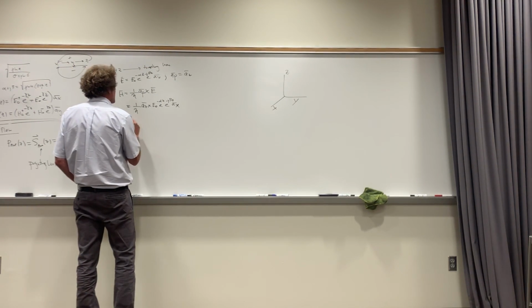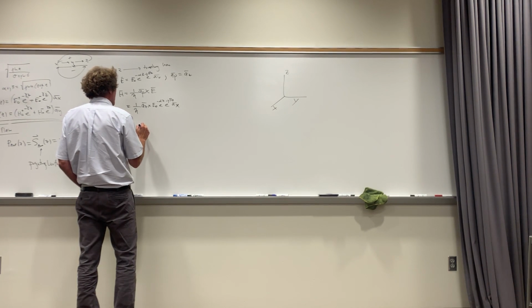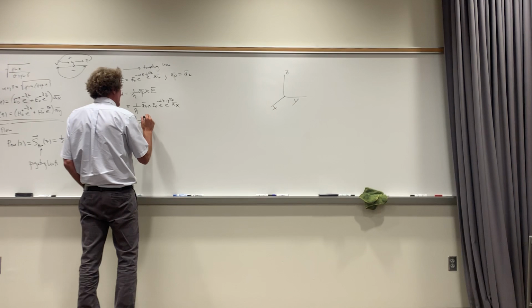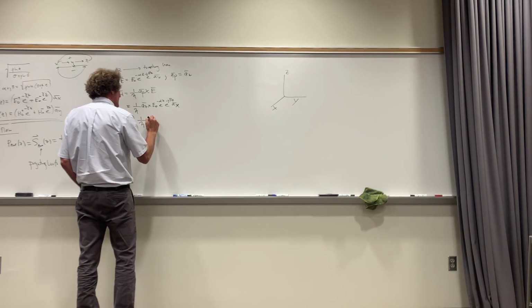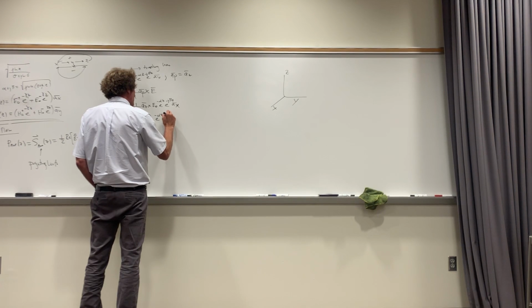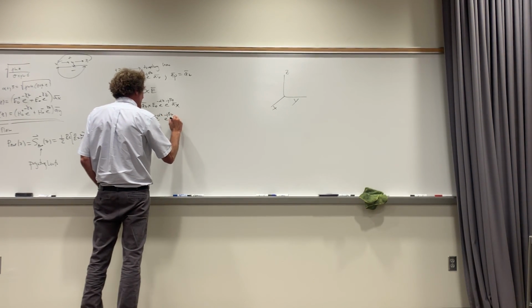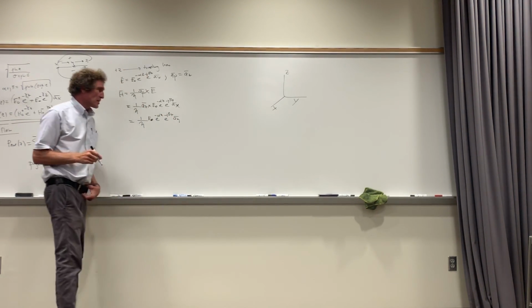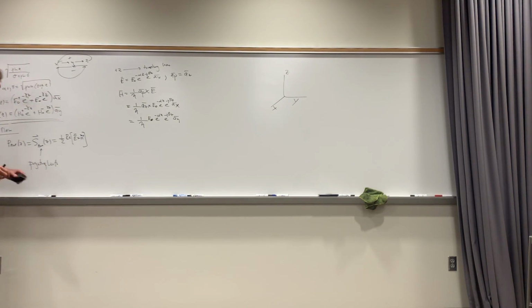And that means this is going to be equal to 1 over eta, and it's going to be E naught, right here, e to the minus alpha z, e to the minus j beta z, and then it's in the ay direction. I'm going to make one other comment right here. It's important to listen to me. Now, eta has a magnitude and an angle.